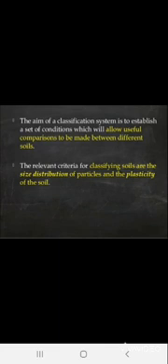So what does that mean? If we have a soil that is sand by nature, and on the other hand we have clay, whenever we compare both soils, the main difference is how they will behave on the implementation of the load. As usual, sandy soil provides maximum drainage to the water, but in comparison, clay particles are very fine in nature and do not provide any type of drainage to the water. So as loads are applied to these different soils, their behavior is also different because of their nature and drainage.